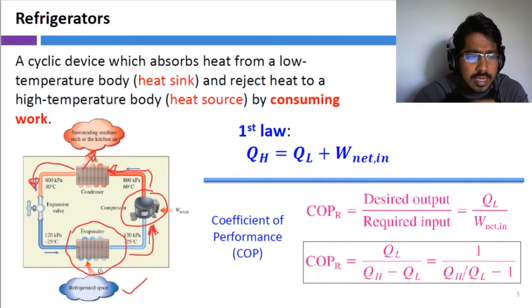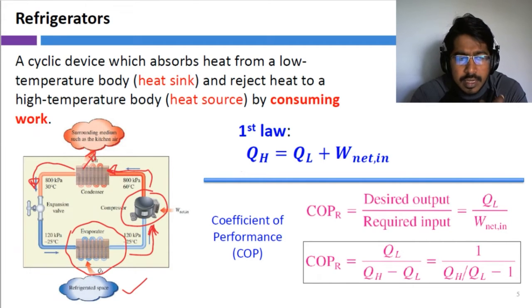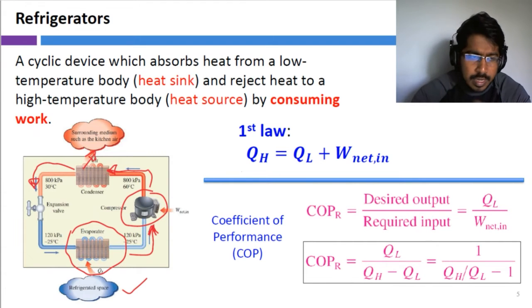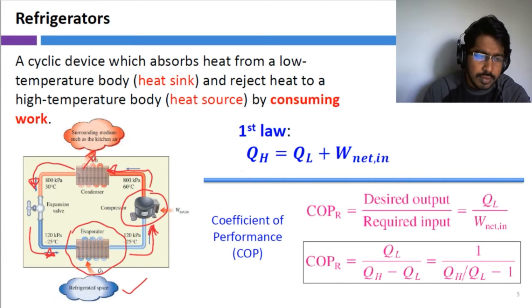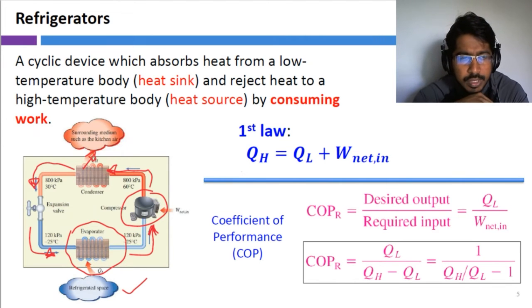As we learned the other day, what an expansion valve does is a pressure drop without enthalpy change, right? And then there we drop the pressure and go again to the original conditions which we started with, and the cycle continues throughout, right?